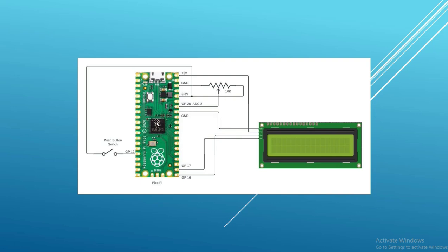The internal temperature sensor is in the chip on the Raspberry Pi, and it will also be used as a source of data. Once these three devices are read and some software processes them, they will be sent over the I2C bus to an LCD display.